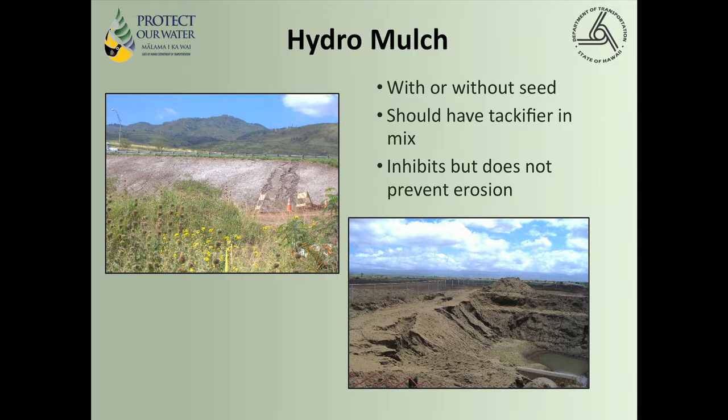When an inspector comes out and looks at your slope, the first thing that's going to catch their eye is the eroded area. And then they're going to start looking to see what else you have in that area. This particular slope, there were no interceptors. There was nothing at the top of the slope.